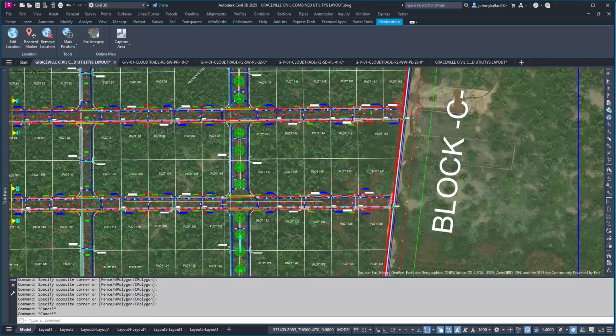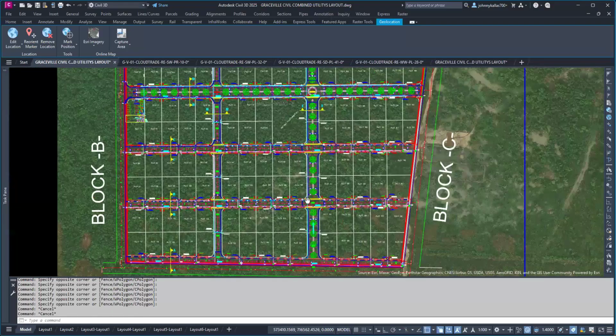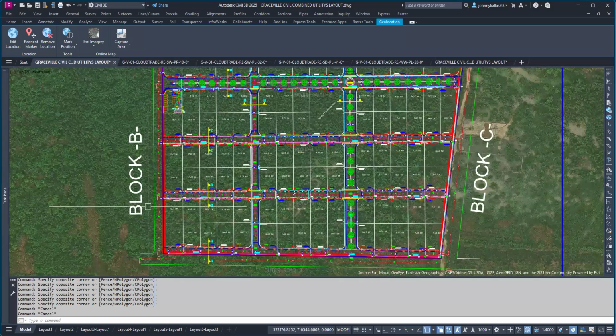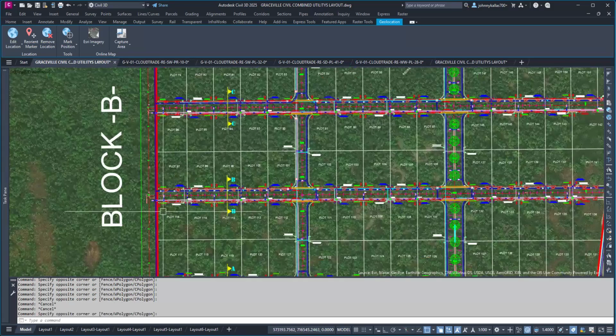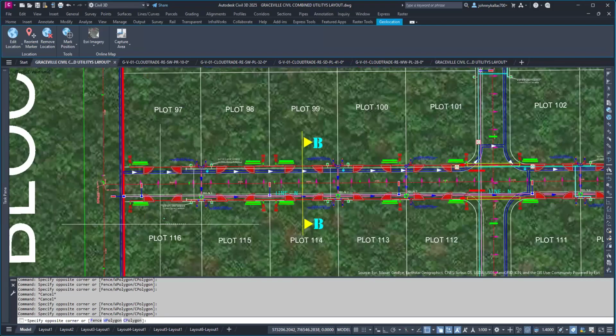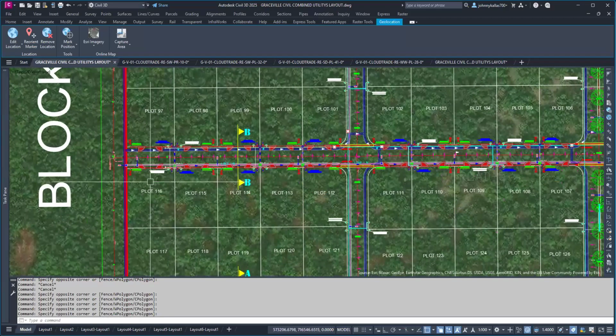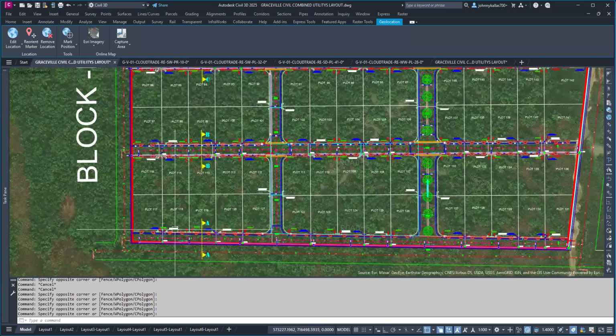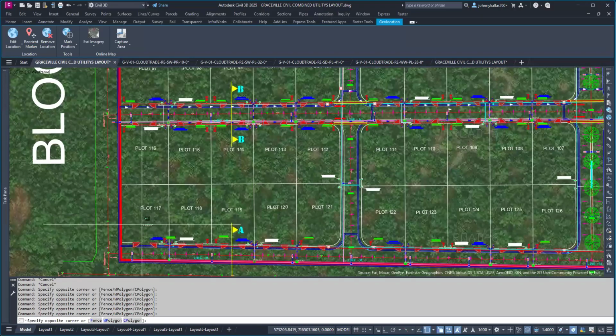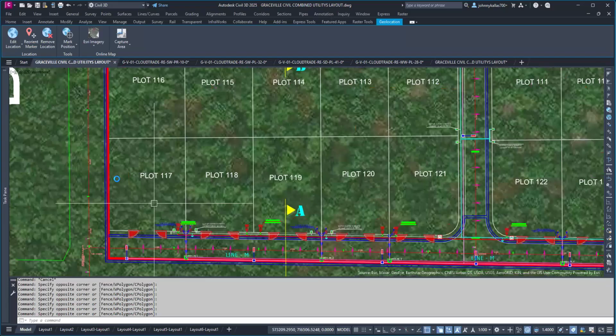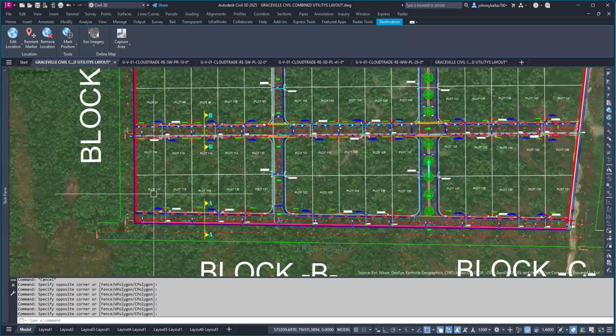Yes, I understand your point, but when you are doing your ground beam, your edge ground beams, you need a light filling, an initial filling for me to hold the base of the foundation of your beam. You don't just, because it's very deep. You know, if you're going to fill, let's say 3 meter high, by the time you have filled the crest, it will spill over to the plots before you now start to talk about your ground beam to edge the sand, because you cannot sink your ground beam at the natural ground level. It has to be on the sand fill level, isn't it?